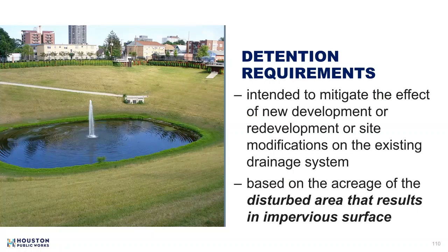So nowadays, what we constantly hear people say is, yeah, but the impervious cover, the concrete in my parking lot, they are exactly the same. So why do I have to provide detention? Well, because now detention requirement is based on a disturbed area, not whether you increase or not.